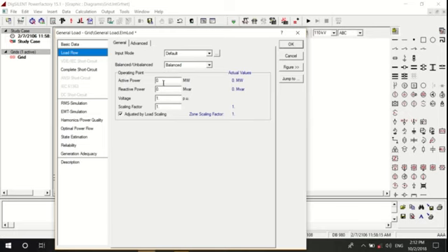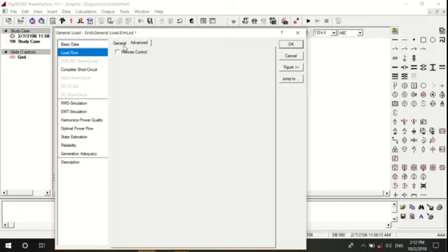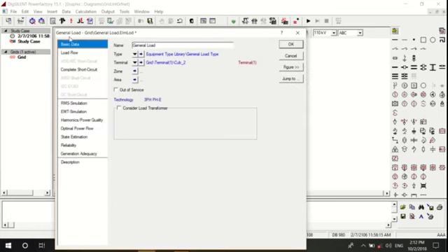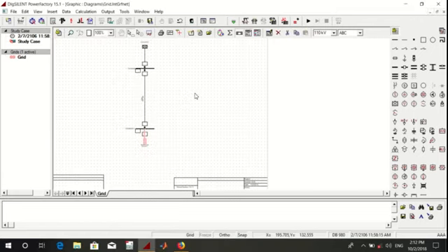Here we gave some values for the active power, for example 9.434, reactive power of 4.63, voltage per unit and scaling. Okay, if you want to have remote control of these loads, we tick mark this and define it. Here we do not, hence just okay. Now all the components are connected. Here all the parameters for each one have been defined, hence we go to calculate.